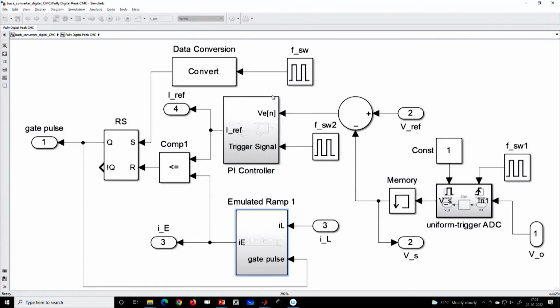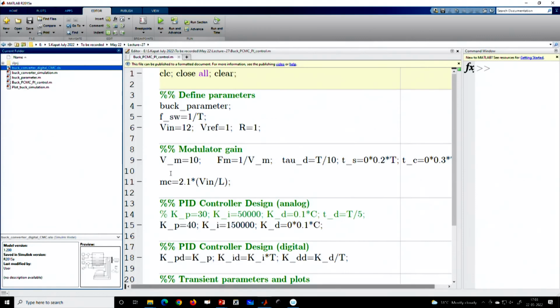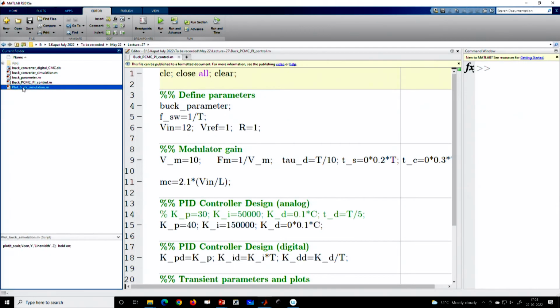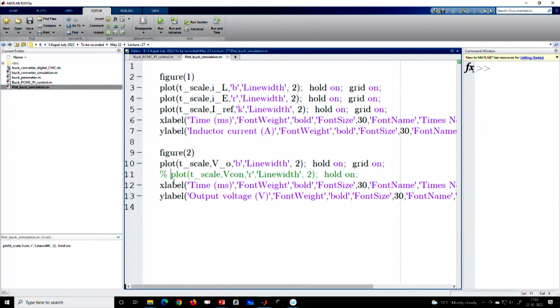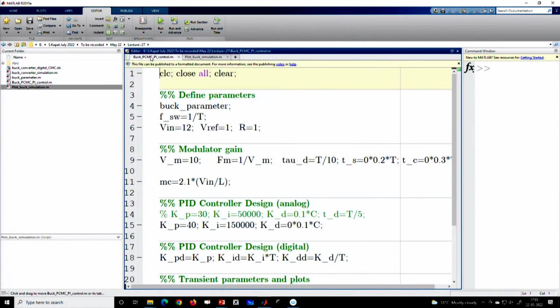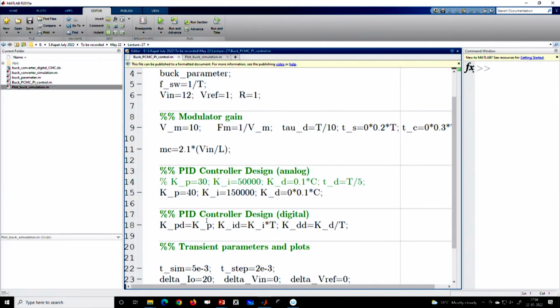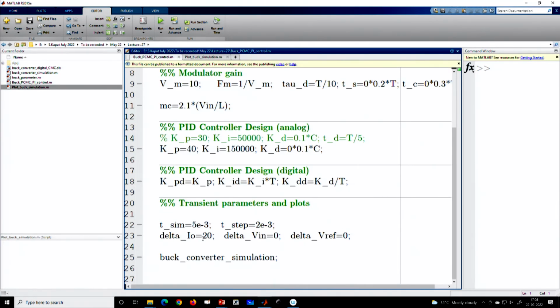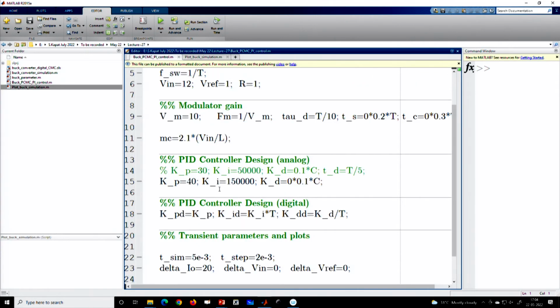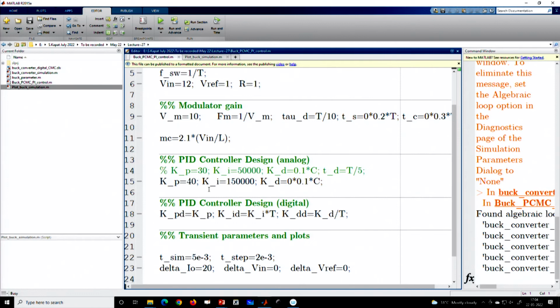Okay. So, now let us go to the MATLAB and try to understand. We will simulate a few case studies. First I want to show a peak current mode control with a delay, where we are again using a load transient and we are not using a very large gain. So, let us first run the simulation and I want to show you all the signals.